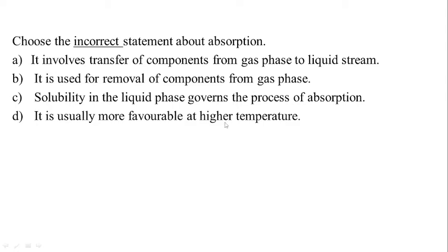Option D. Why is it not favorable at high temperature? Because the absorption process is an exothermic operation. So at a high temperature, the solubility of gas is low.